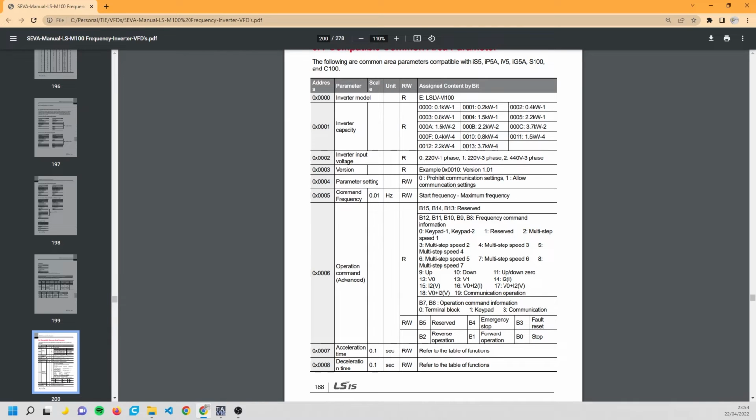Now, this can throw you a bit because coming into this fresh and just looking at it, you would expect, this is hexadecimal 0001, you'd expect this to be an input coil because it's around the low end. This is not the case with this. I've used this VFD before, I know it. You just have to have a play. Sometimes they are, sometimes it is legit the input coils or something like that. This is all assuming an offset of 40,000. So where you see hexadecimal 0001, it actually means 40,001 offset.